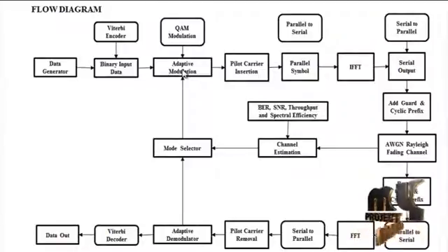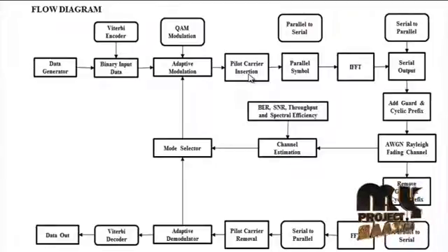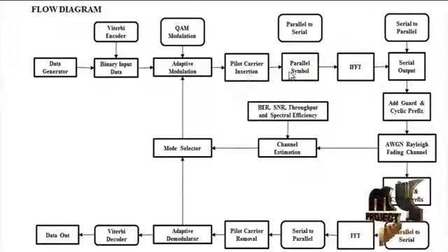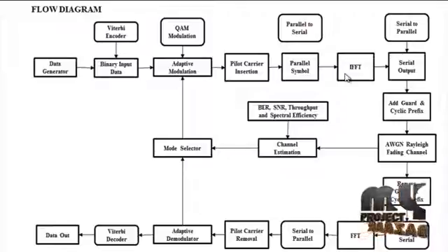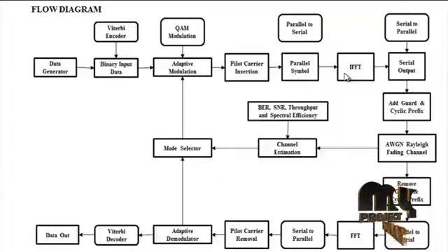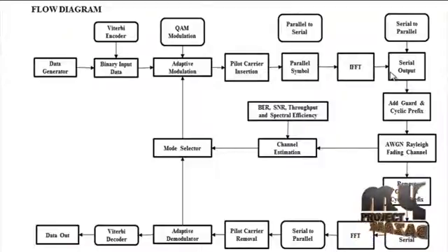The adaptive modulation scheme is used for modulating the input signal, for which 16 QAM, 64 QAM and QPSK modulation schemes are used. In block type pilots, all the subcarriers in some OFDM blocks, the whole spectrum, are reserved as pilot tones. In comb type pilot models, some predefined subcarriers in each block serve as pilots. The Fourier transform breaks the signal into different frequency bands by multiplying the signal with a series of sinusoids.